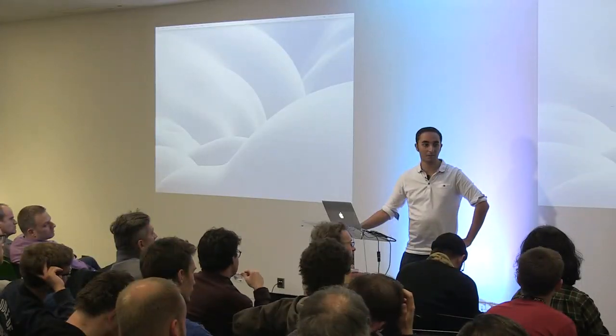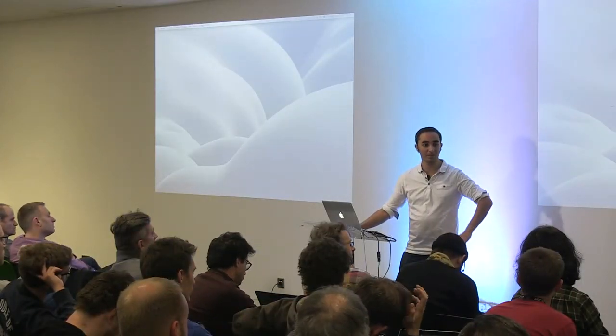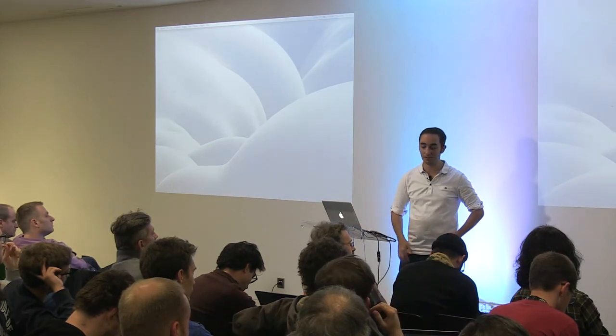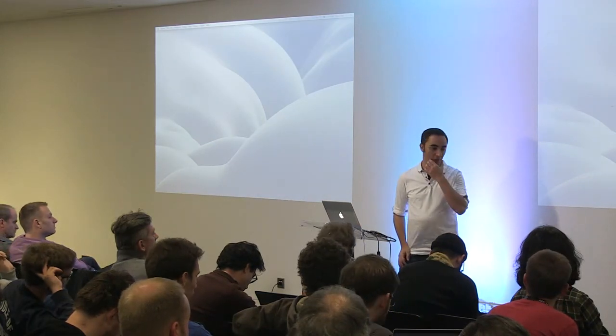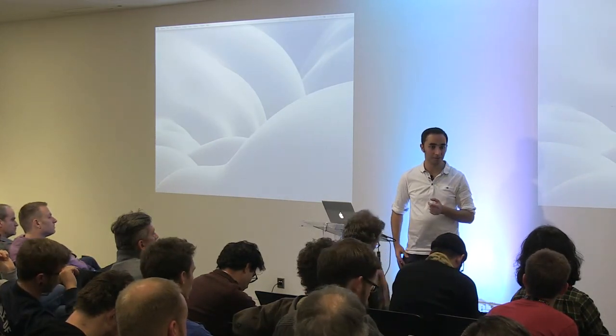We do have a lot of methods to solve the nonlinearities in time without being CPU hungry, instead of Newton-Raphson. So I was talking about the lookup tables. Something we do a lot also is looking at the shape of what is in this lookup table with pre-calculated stuff, and we try to find a function which replicates the shape of what is inside.